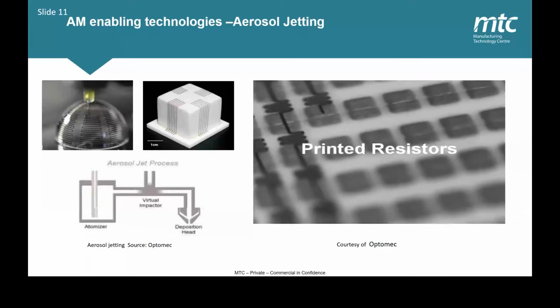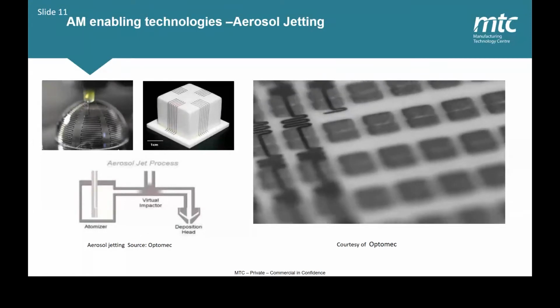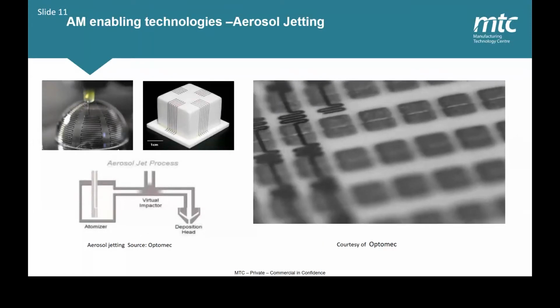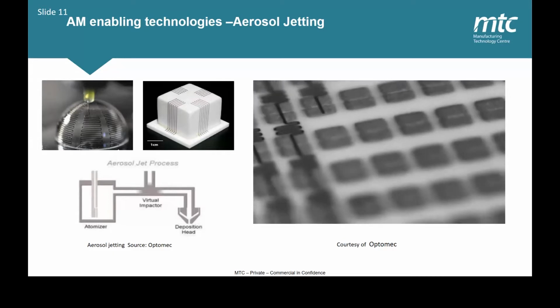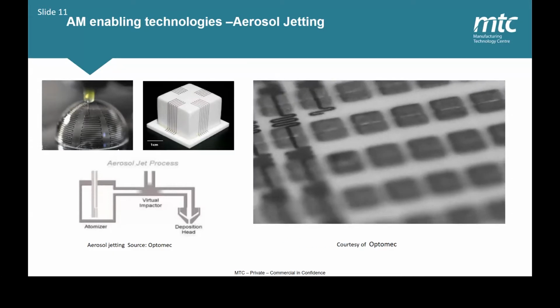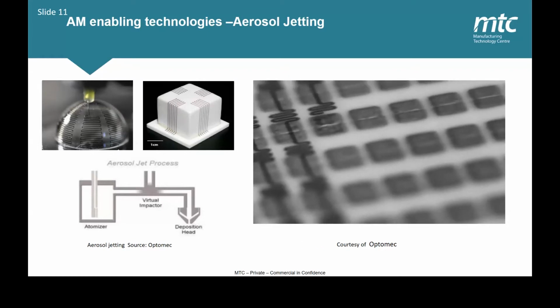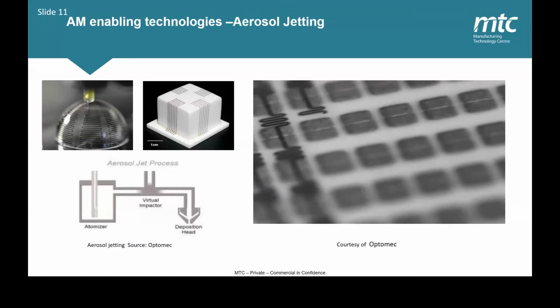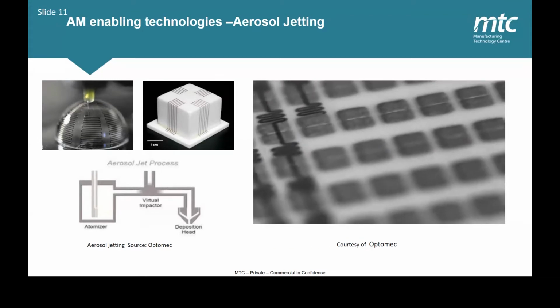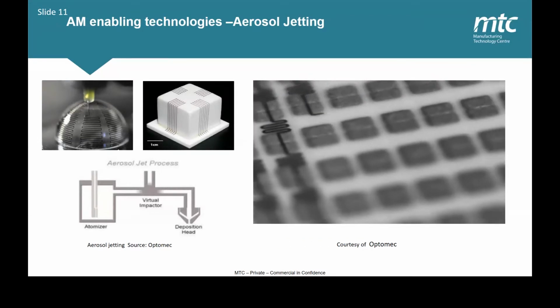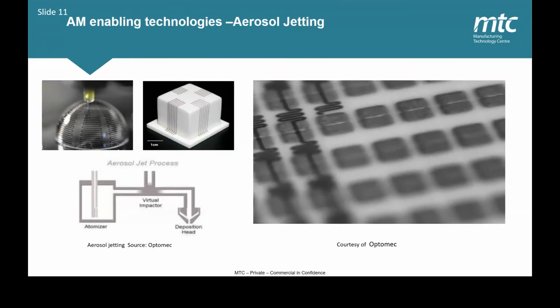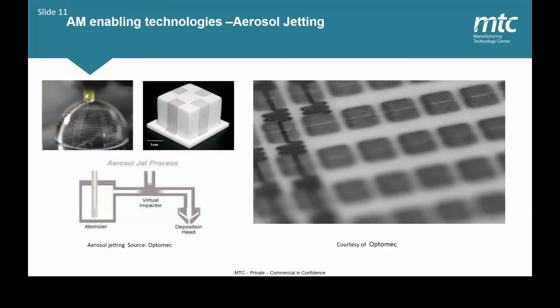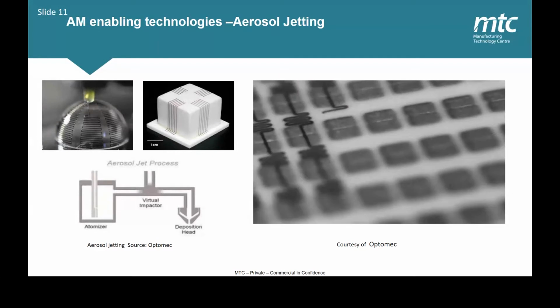The patented aerosol jet process utilizes an innovative aerodynamic focusing technology to produce electronic and physical structures with feature sizes as small as 5 microns. This can produce a wide area conformal coating. The aerosol jet system supports a wide variety of materials, including nanoparticle inks and screen printing pastes, conductive polymers, insulators, adhesives, and even biological matter.